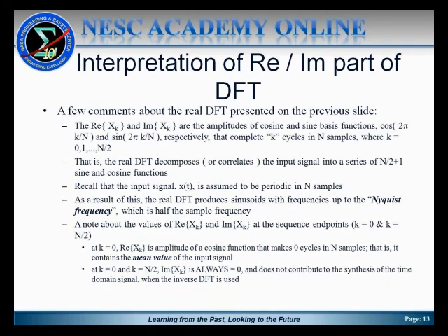So it may look like an oversight. Somebody forgot to include those 2 points. Well, if you included them, they have a value of 0, so it wouldn't have mattered anyway. But that's another little bit confusing factor. If you try to look at the synthesis equation, like in a textbook, you'll see the summation indices for the imaginary part is different than the summation indices of the real part. And that's the reason that the imaginary part is always 0 at k equals 0 and k equals n over 2. That is the ends of the discrete Fourier transform coefficients.